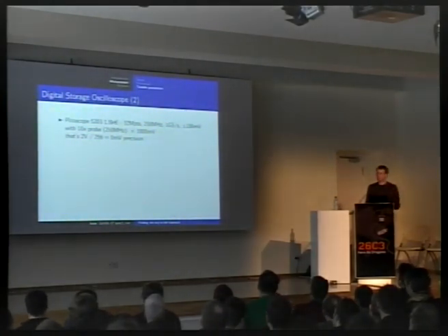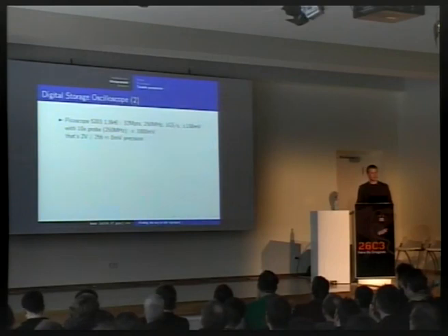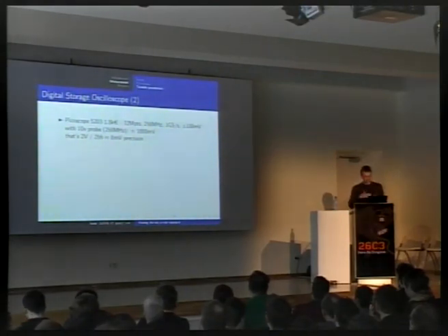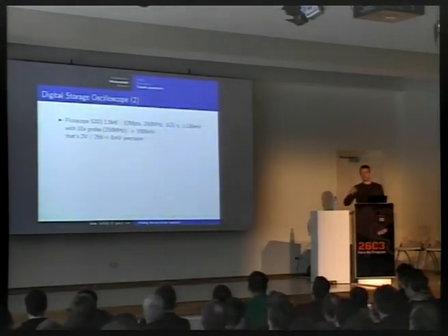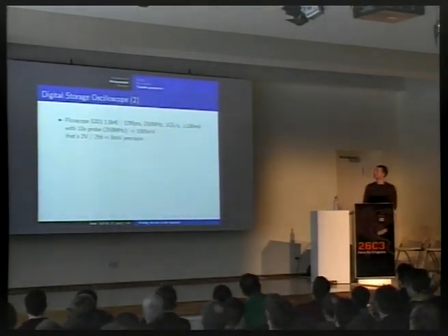Well, the PicoScope is a storage scope that isn't quite so in the high price range, though it has a quite good sample buffer. It has 32 megapoints, that is usually quite expensive, and 250 megahertz analog bandwidth. You have 1 gigasample per second, and it does a 100 millivolt range. To get this bandwidth with the 10 times probe, you have to use the division setting 10, so you'll only get 2 volts, and this precision is not very good anymore.